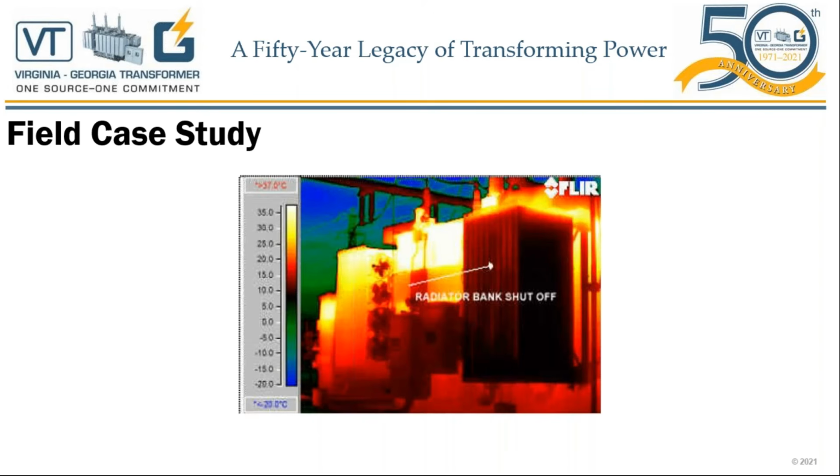Okay, on this slide, I'm not going to say anything. The picture is very clear. The radiator bank was shut off. So the oil was not going through the radiators to cool the transformer. So the transformer was running pretty hot in this case.